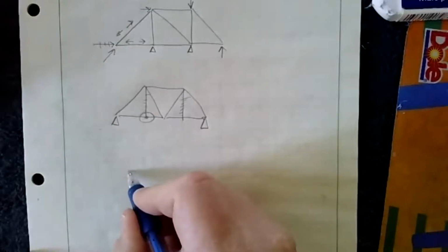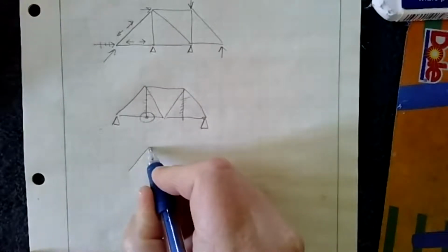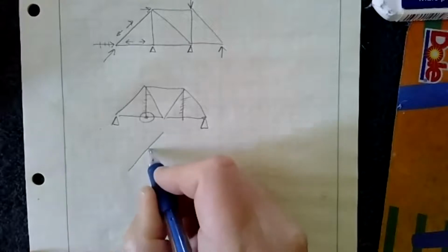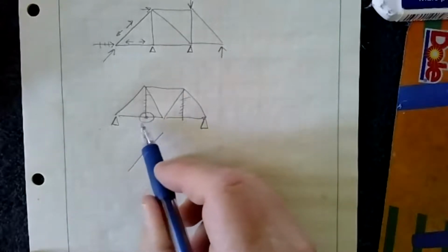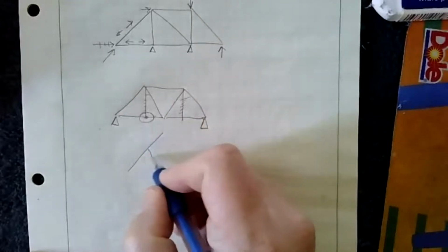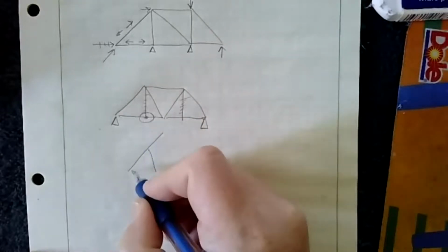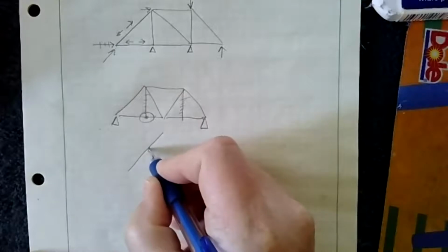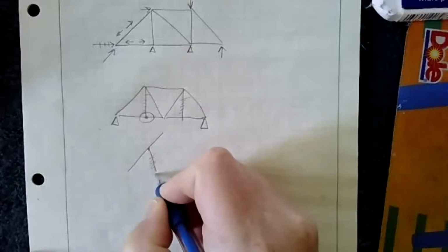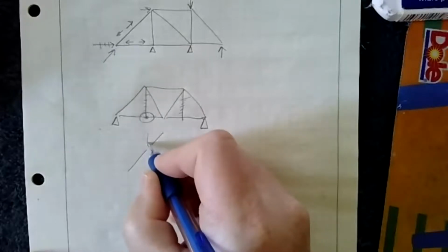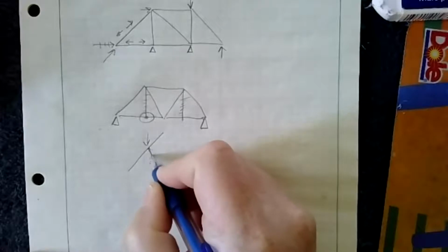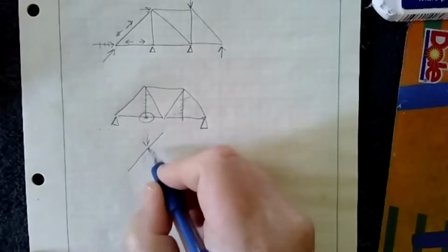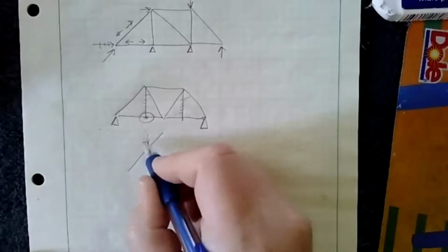Sometimes you may have something that looks like this, and there'll be one member like that. So it doesn't necessarily have to be normal to it. It doesn't have to be 90 degrees. It could be any angle. But anytime you have a line like that where there's another truss, another member intersecting, this one has to be zero force. Now, if we apply a force here, then this is still active. Then that changes. But again, this is criteria with no external force.